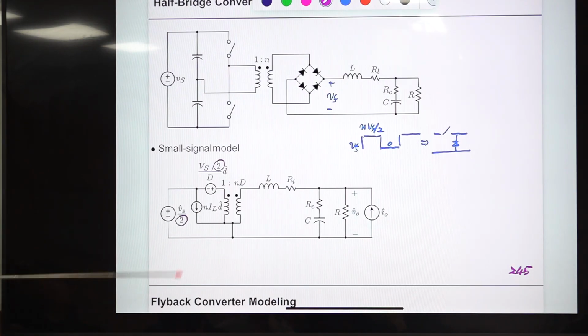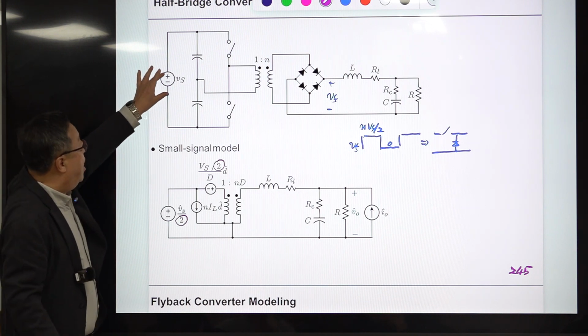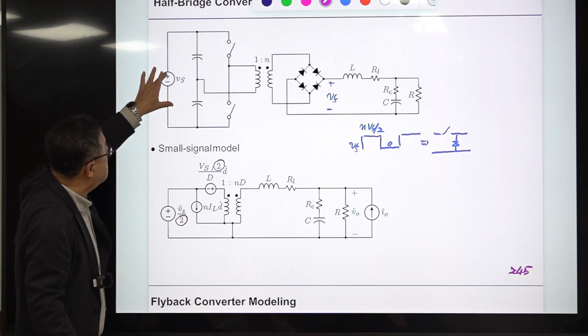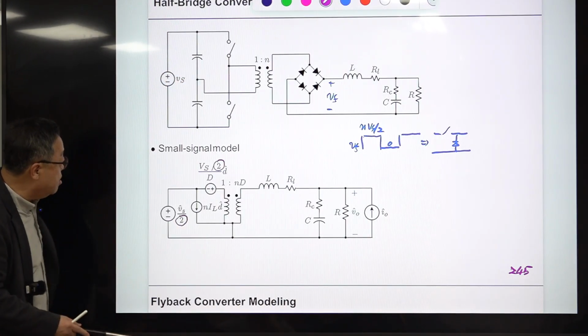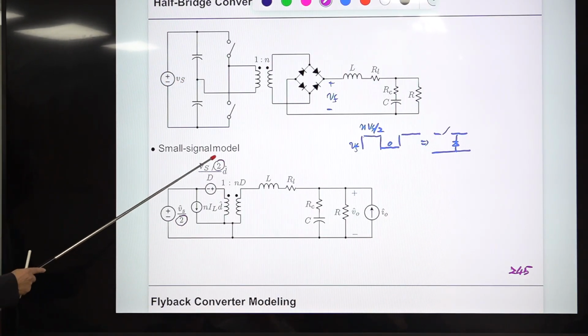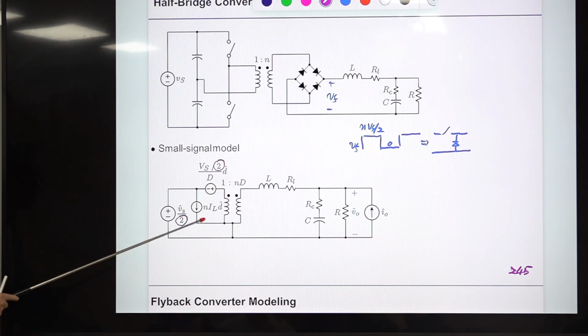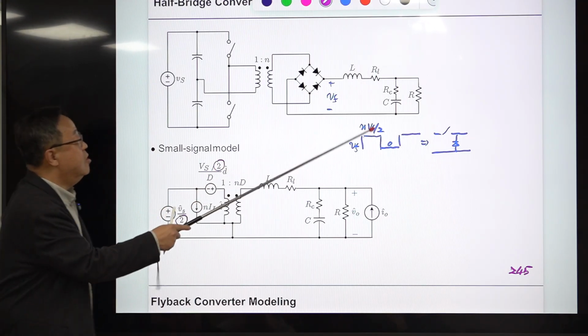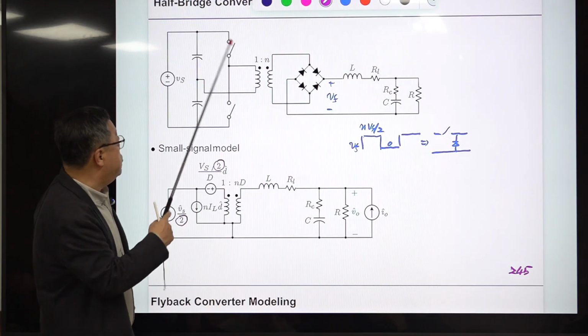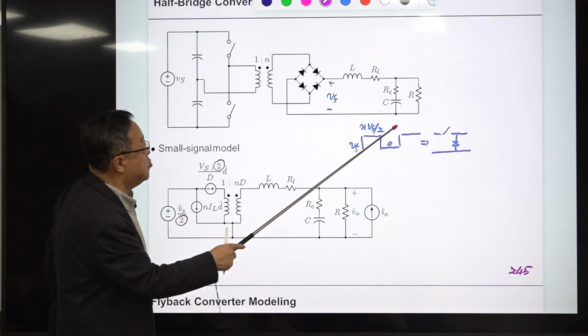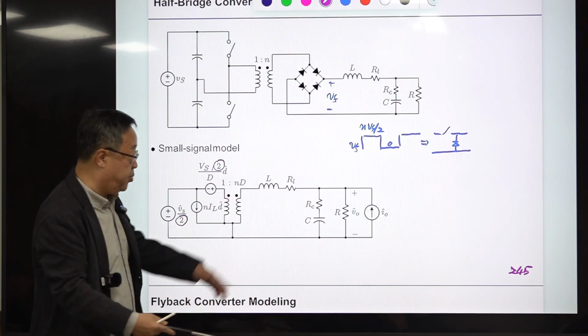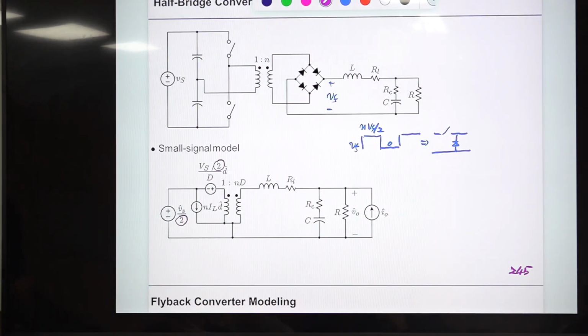Half bridge converter, this works as the voltage divider. So this is the same as if you have two voltage sources, half the VS here, half the VS here. It remains the same, and you only have a factor of 2 here and here. It's obvious. Also, if you analyze this, the voltage here is this one, and this is replaced with the PWM switch.